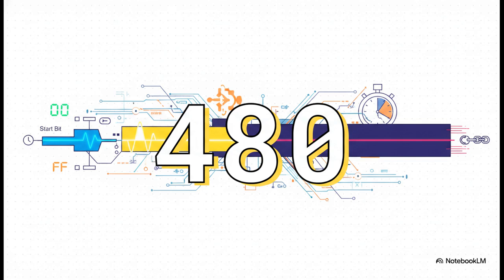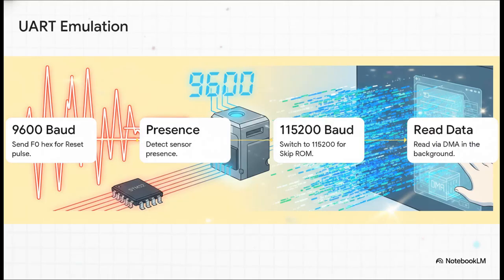Waking up the sensor in the first place requires a strictly mandated 480 microsecond low reset pulse. And honestly, that is physically impossible at our normal 115200 UART speed. Which leads us to what I think is the ultimate embedded hack. First, we temporarily drop the UART baud rate way down to 9600. At this incredibly slow speed, sending the byte hex F0 stretches out the low bits into a massive 520 microsecond reset pulse. This completely fools the sensor.